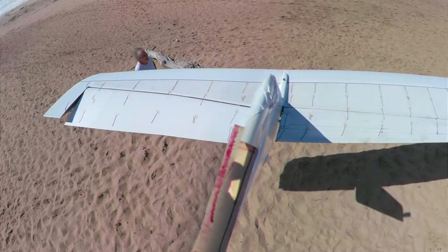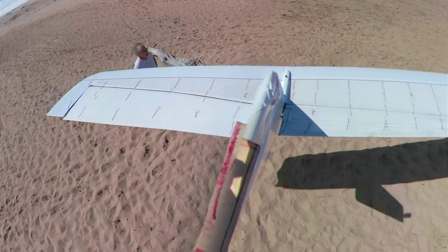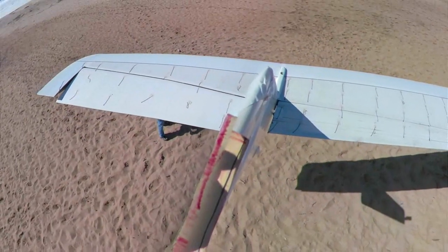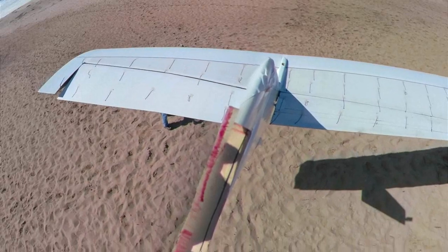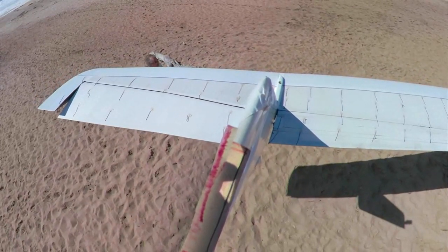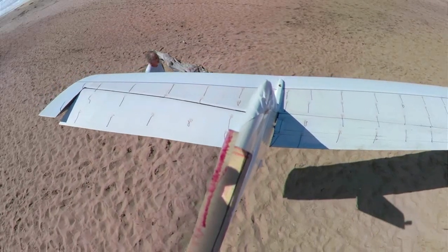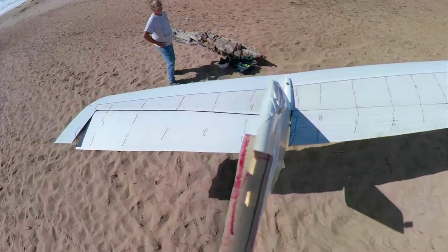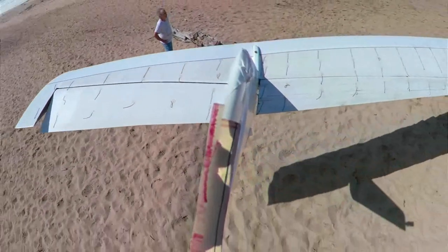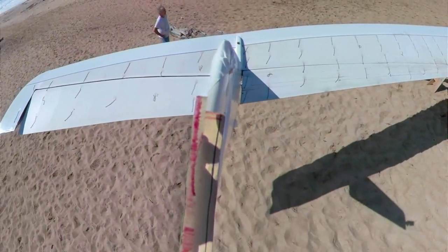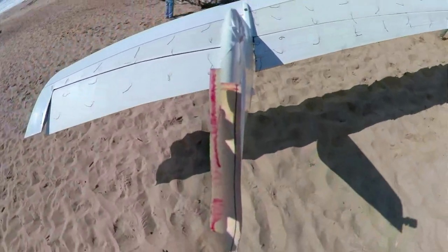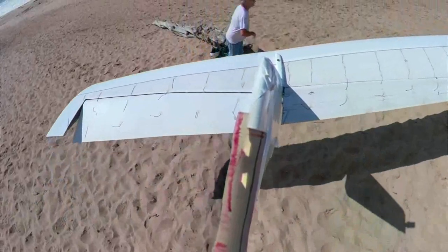And we're at the beach again, and I'm going to do some little ground runs here. But first, I'm just doing ground handling in place here. And it was fairly easy to ground handle. However, that big chunk of elevon that I added out on the wingtip panel weighs quite a bit in terms of everything else on the wing, and it about doubled the control forces on the stick. So my plan at the time was, when I get home, I'll just put counterbalance weights on it.